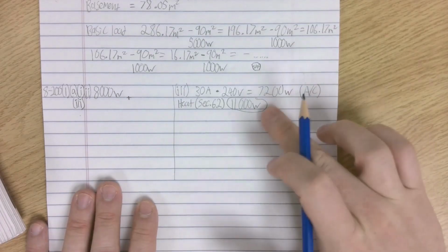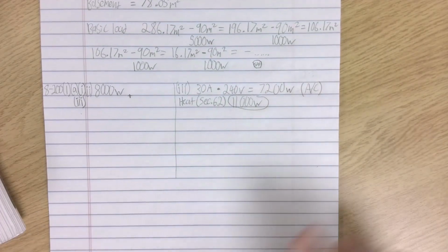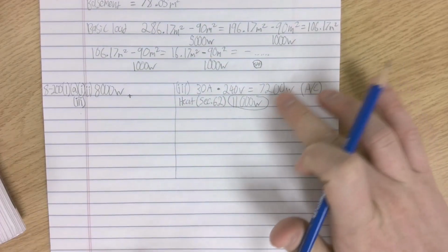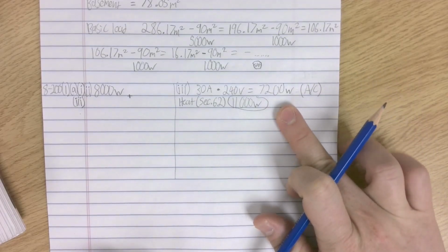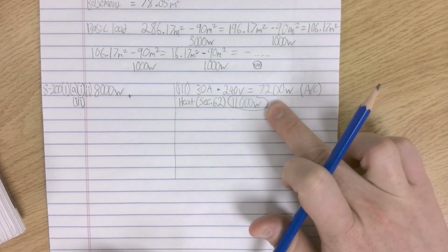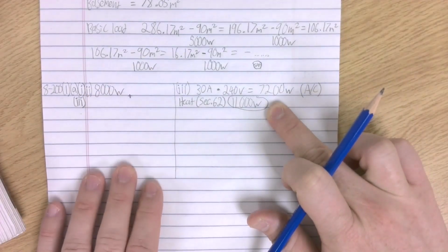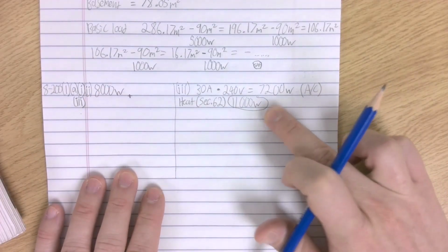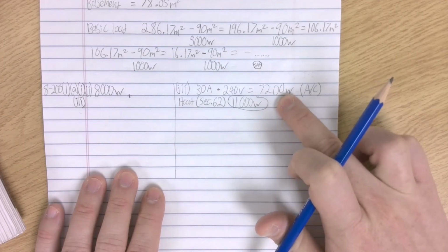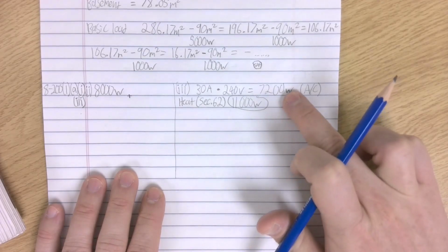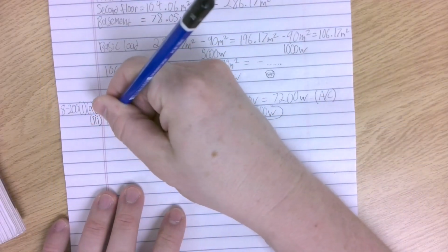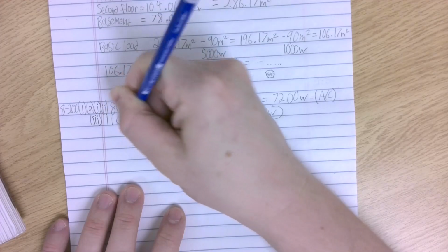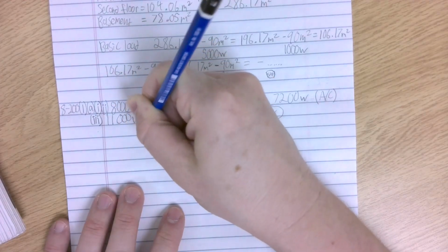And because they're interlocked, if we just think about this logically for a second, only one's going to run at a time, right? So if we size the entire house calculation towards the larger load, that's going to make up for the other load, if that makes sense. Hopefully that makes sense. So 11,000 watts gets added under item 3. There we go. We're cooking now.